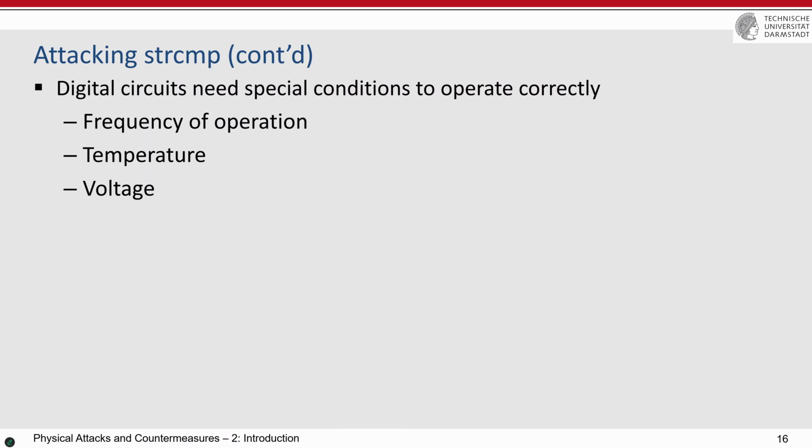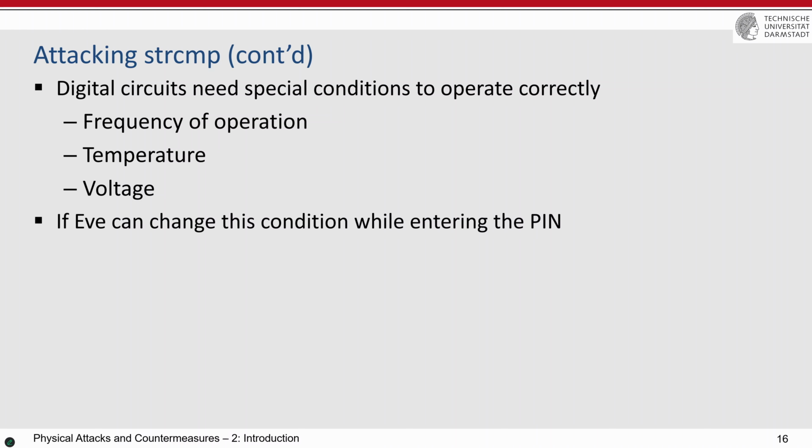We inject a fault into the device, and then we use the faulty outputs to perform the attack and recover the key. For example, here in this example, that's the USB stick and so on. If we inject a fault by changing the frequency, clock glitch, or voltage glitch for a short time, changing the power supply of the chip, what usually happens in microcontrollers is that some instructions can be skipped. Instructions executed by the processor can be skipped.